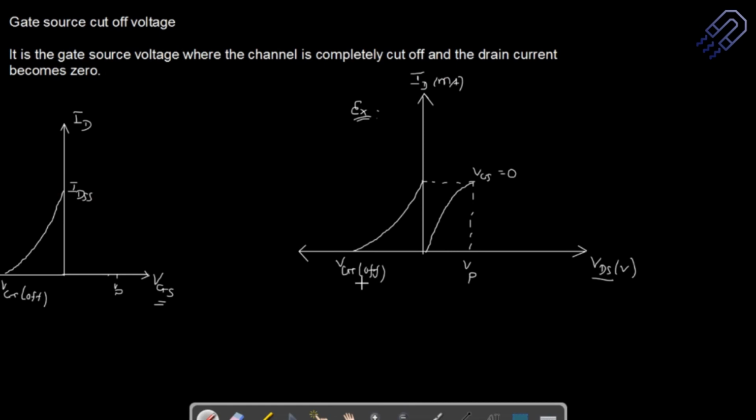Okay, so this is the cutoff voltage. This much region and this much region are the same, it just doesn't look that way on that scale. So this is a good example that we can take, and I can write it down as minus VGS in volts. VDS is 0, VGS is taken to the minus scale, and then we are going to see that we have this cutoff voltage.